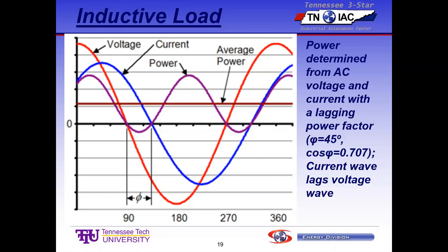Well, guess what? They'll penalize you for both. I've seen bills where in the same month they charged a leading and a lagging power factor penalty. What usually happens is the lagging occurs at maximum demand and the leading occurs at minimum demand.